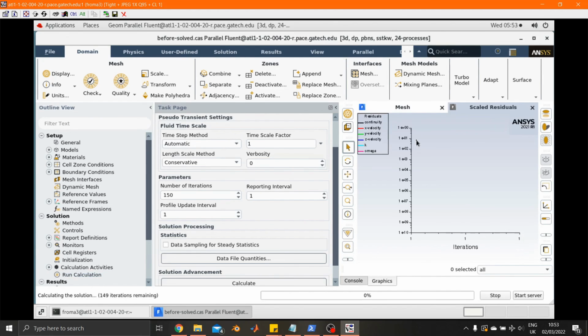And the smaller that gets, the closer you are to the solution. So you'll see here a lot of these colorful lines will pop up, start quite high, and then go lower and lower and lower as the residuals get smaller and smaller. If they all go below 1e-3, it stops the solution automatically and it's done. But they don't all have to go below 1e-3. It might stop at around 1e-2. That will still be fine.